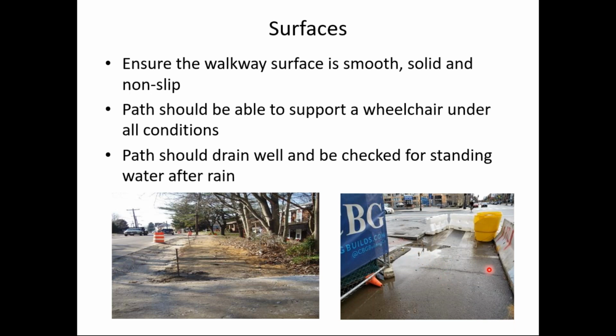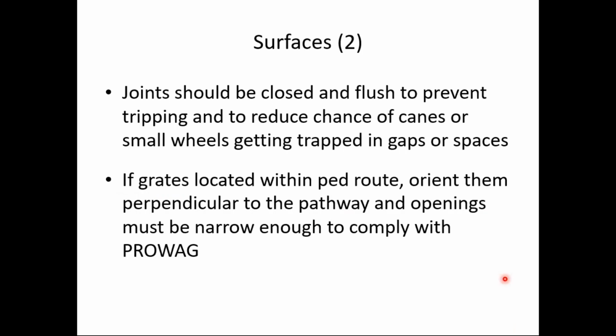And actually, the day I was here, just after I took this photo, a fellow in a business suit and dress shoes showed up, and he attempted to jump over this water. I guess because of some of the sediment and the wet pavement, he lost his balance, and another pedestrian reached out and grabbed him to prevent him from falling. So my point is, there's a case where even an able-bodied pedestrian experienced some safety issues at something like that. So try to pay attention to the standing water and sediment or mud at the base of your ramps.